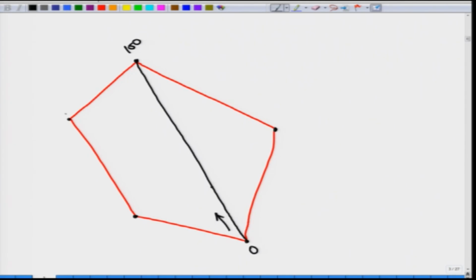So, what you have done is that you have added stakes on all of these points for which you want to take measurements, and now you are moving from 0 to 100, and you reach a point where you find that the first point is exactly to your left. So, it is making an angle of 90 degrees, and you now have reached this position. This is your first position, so let us call it position A.